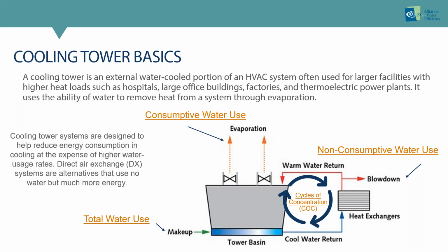So this is the key metric for water efficiency, the cycles of concentration. So we can't infinitely let solids build up. So we do have to balance other issues like managing scale buildup, corrosion, biological growth, and more. So really, typically the main focus to achieve water efficiency is to increase the cycles of concentration by reducing the blowdown and therefore reducing the makeup water needed.